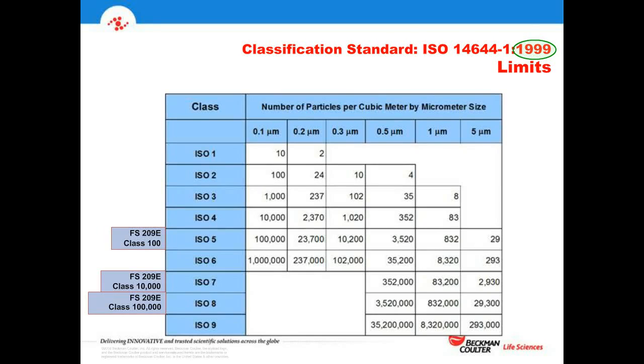In the standard, there are 9 different classes of rooms, ISO 1 through ISO 9, going from very clean at ISO 1 to not very clean at all in ISO 9. Most operations tend to be in the range from 5 to 8. But not always. It depends on the particular type of industry and method. Certainly, the semiconductor industry utilizes ISO 2 and even ISO 1 at times. Very demanding, but